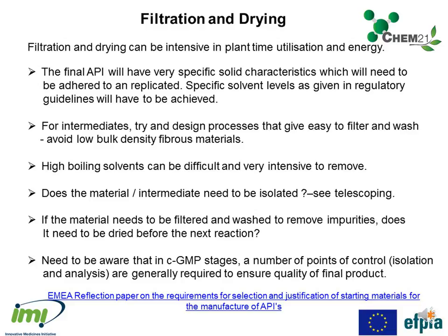Filtration and drying, again, most intermediates and final products are isolated as solids. This is a very common set of unit operations. So these can be intensive in terms of plant time utilization and energy. So we need to bear in mind the final API will have very specific solid characteristics which will need to be adhered to and replicated. Specific solvent levels as given in regulatory guidelines will also have to be achieved. So obviously drying is very important here.